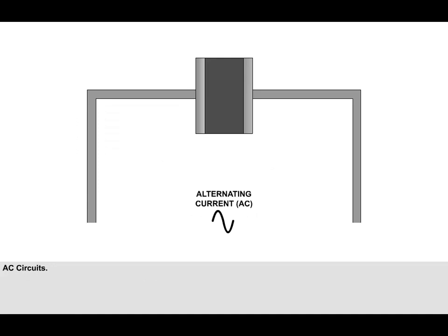Much of the electrical power used on aircraft is alternating current, or AC. In AC systems, the polarity of the supply voltage changes cyclically. The change happens at a much greater rate than shown here. In fact, in aircraft AC systems, it changes 400 times every second.